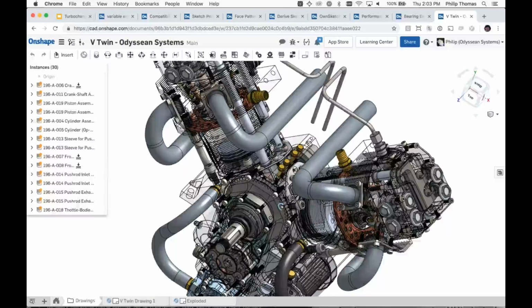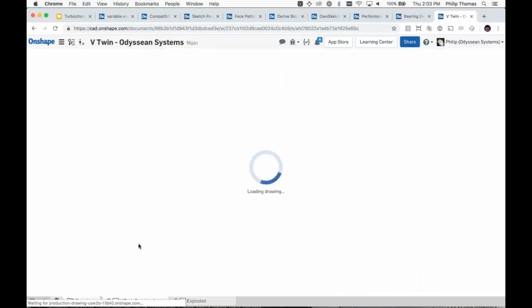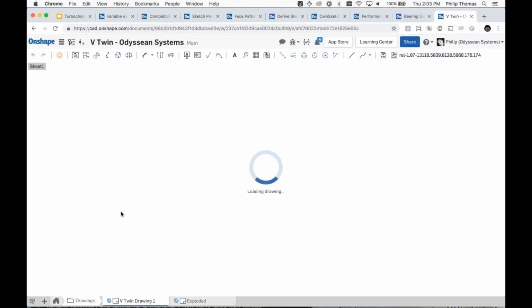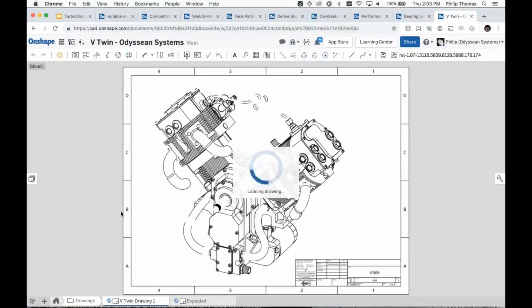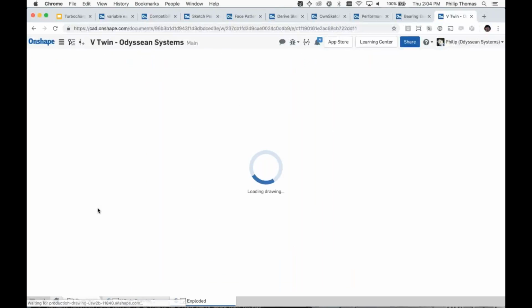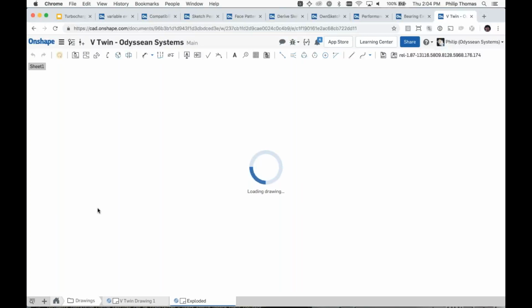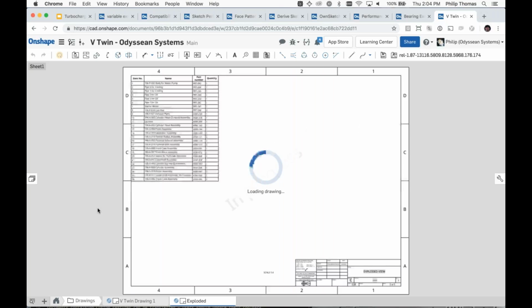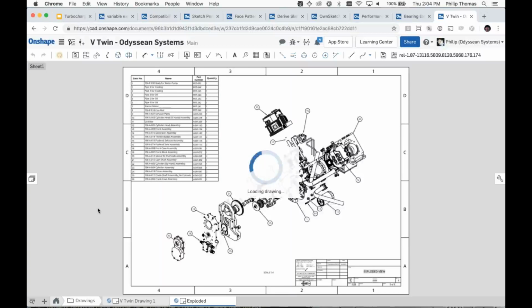And then, of course, for the drawings, notice very, very clearly, these drawings are referencing versions of the assembly. I'm not pulling this over in real time. I can go ahead and detail this section there, put bills of materials on, do whatever I need to do. If and when a newer revision or version becomes available, feel free to switch to it. This one takes a little longer. It's the exploded view. So there you go. And I'm sure this is opening faster than many of your drawings. And the reason is I am referencing a version.